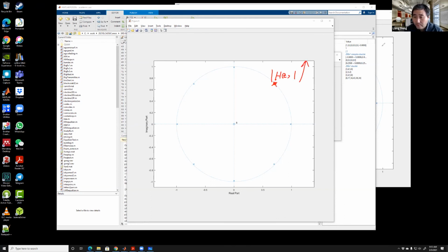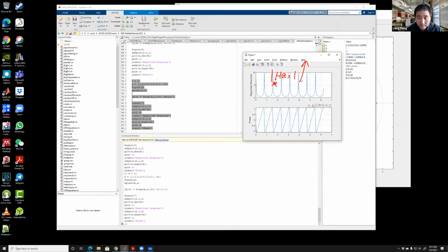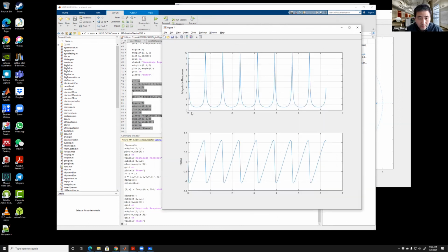And then lastly, what we see here is the frequency response. That's the last picture. So yes, as we designed, I want to make sure that on those 8 frequency positions, I have a very large magnitude response. I have a very large H(z). So indeed, this is the case. I got those 8 spikes, very large. And you can imagine if I had the poles on the unit circle, those spikes would go upward to the sky. It would blow up very large.